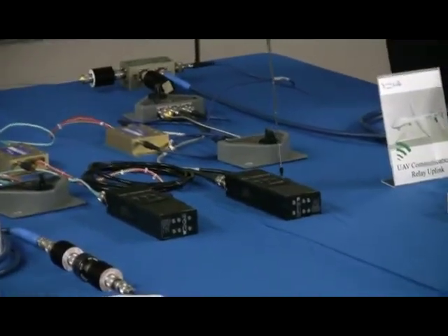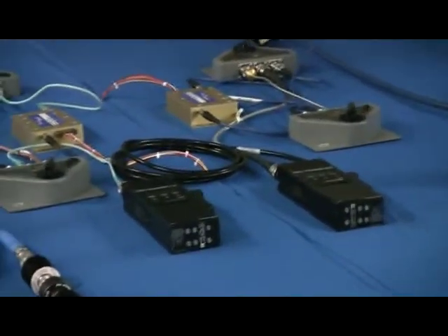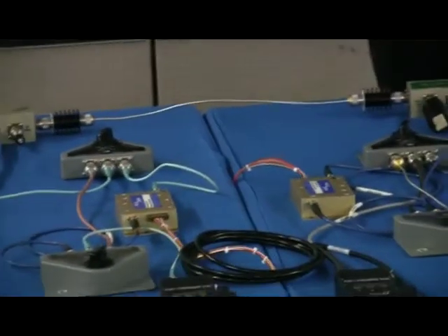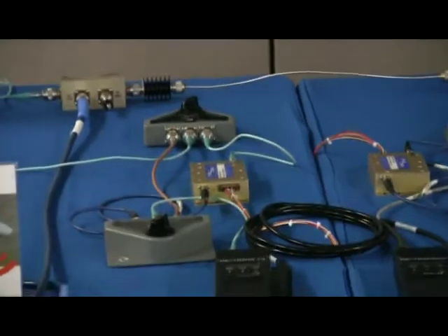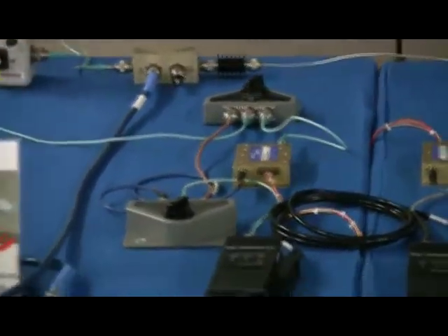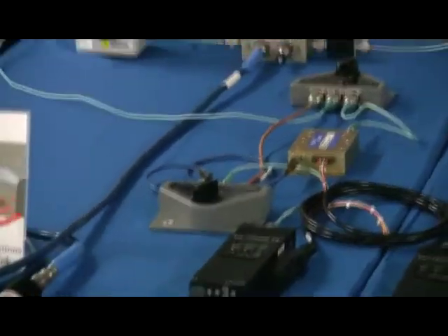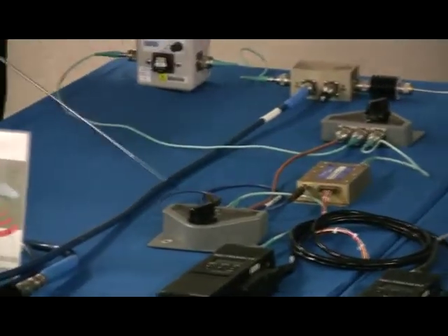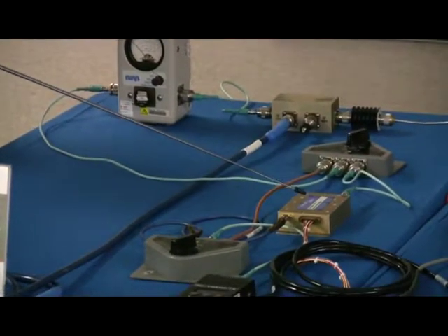Now the uplink receiver's audio output is coupled into the downlink transmitter, which then feeds the downlink system. But recall also that the antennas are coupled with 40 dB isolation between them, representative of the coupling between the receive and transmit antennas on the UAV. So we have this cross-link coupling, if you will, that applies. Once the audio is coupled into the downlink transmitter, it goes again to this switching matrix, which will either bypass again or apply the Cosite mitigation unit on the transmit.